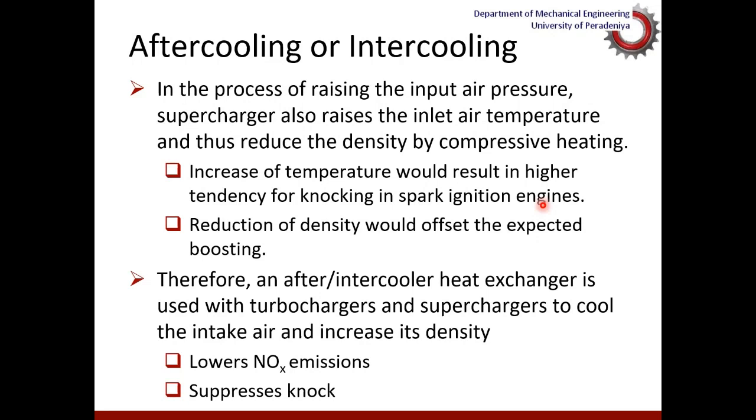So intercooling helps us to cool down the intake air again back to a certain temperature, which will enable the increase of the density, reduction of the tendency for NOx emissions, as well as knocking in spark ignition engines.